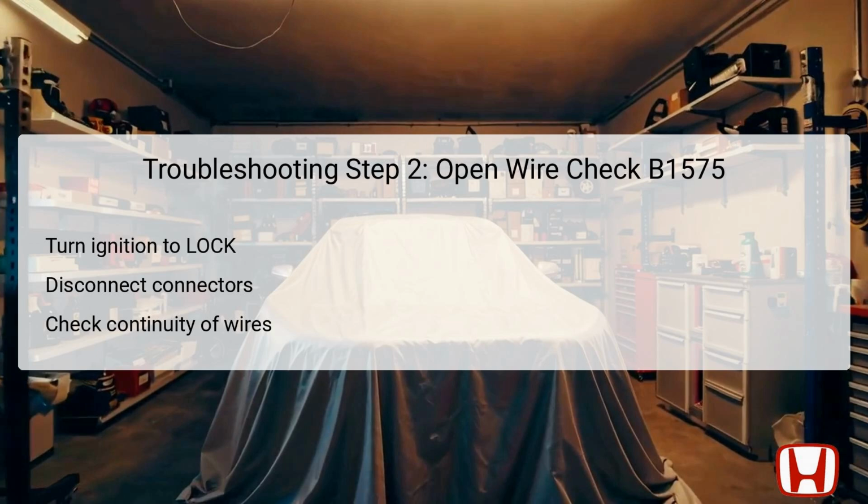Inspect the continuity of the wires by checking connections between the specified test points. This is vital, as an open wire will prevent signals crucial for the operation of the automatic lighting system. If continuity exists, continue to step 3. If not, repair any open or high-resistance wires detected in this circuit.